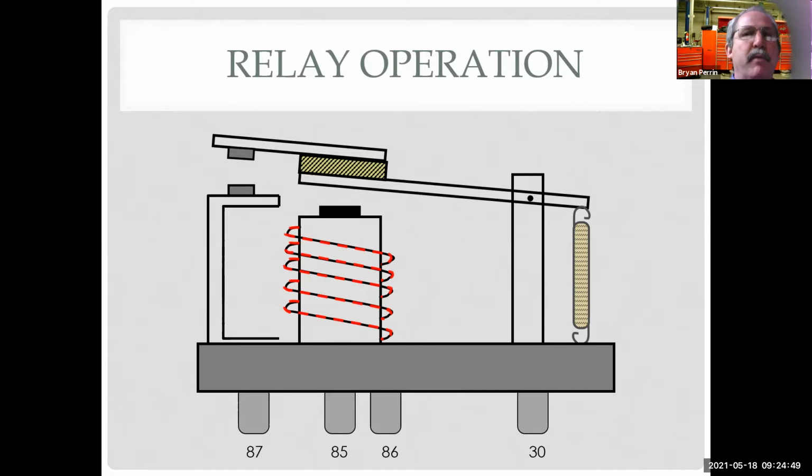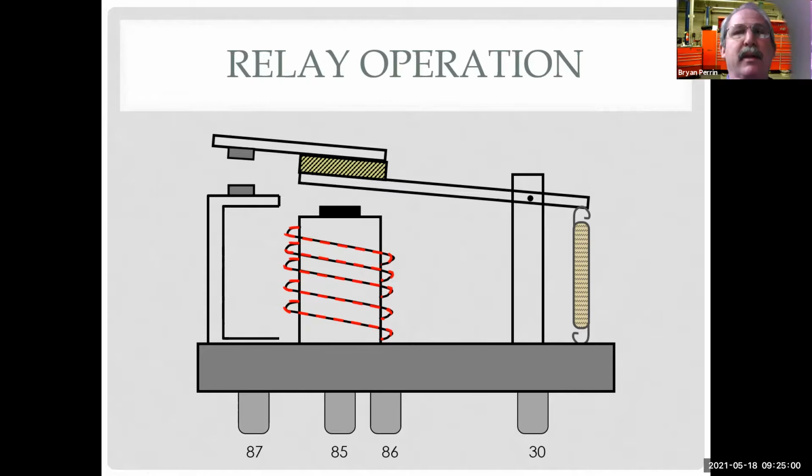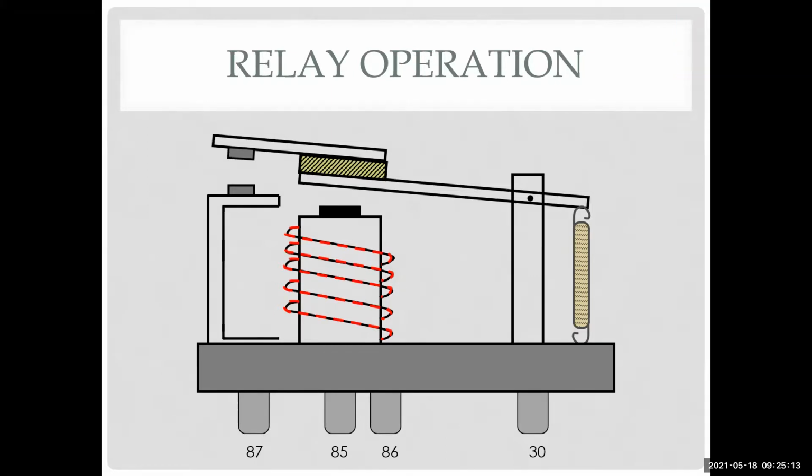So now I don't need to worry about burning out my headlight switch or burning out the wires going to the headlights, because this is a very small load. If I had spliced the driving lights into the wire going to the high beam headlights so they came on every time, or wired them in where I went through a switch to turn them on, now I'm going to probably overload my dimmer switch and my headlight switch and burn them both out. So if you use the relay and fuse, that redistributes the load.